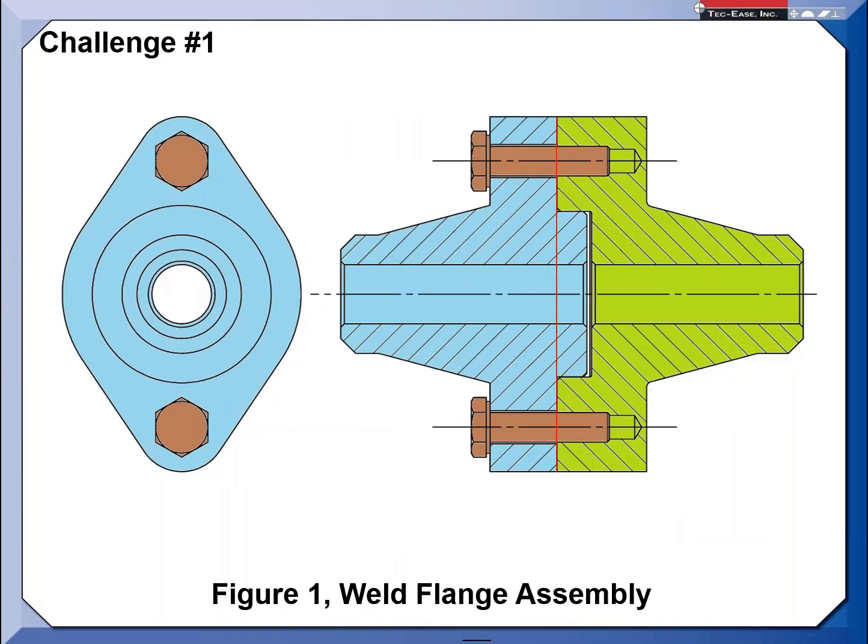So when I bring the assembly together, here's my theoretical perfect mating: nice planar features, all the points in the surface perfectly coplanar, nice linear. And then if you had this type of a joint coming together, and you want to tighten this up, that might be an issue, might be a problem. Again, that is design intent that engineering would have to deal with. And how are they going to control these primary features here? And how do these secondary features relate to the surface variation? So that was just my attempt to explain the datum precedence and how we're doing this.